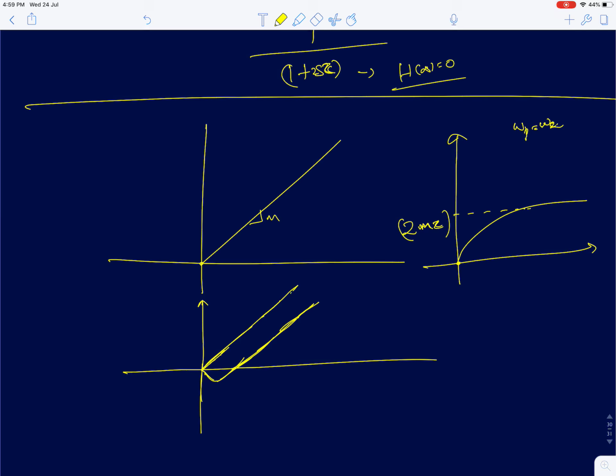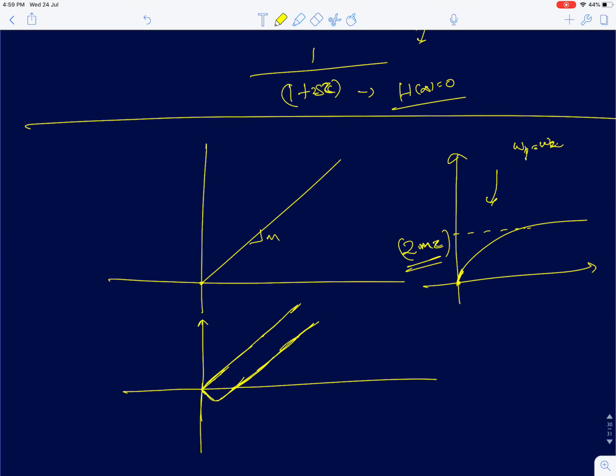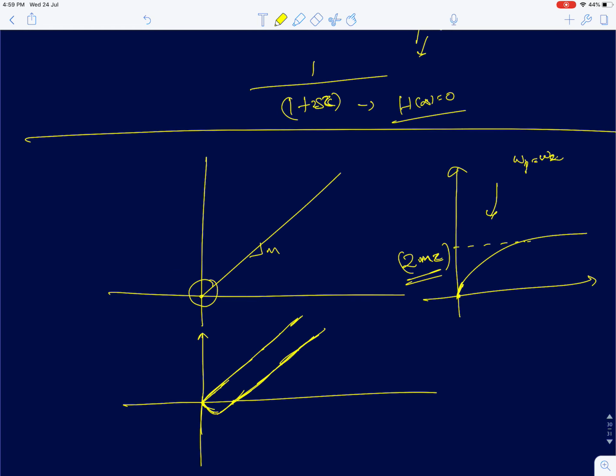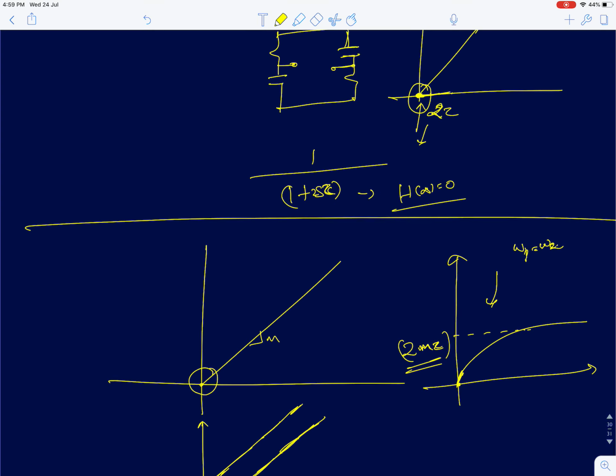So this is your input. Okay, the delay comes from that, because the slope cannot be 0 initially at t equal to 0 for this system. Because this is rising initially with a slightly higher slope, which is actually 2t, and this is initially rising at the slope of t. So when you subtract the two, your response will be like this. I'm sorry, the response will be slightly different. It will actually hit 0, and then revert back.